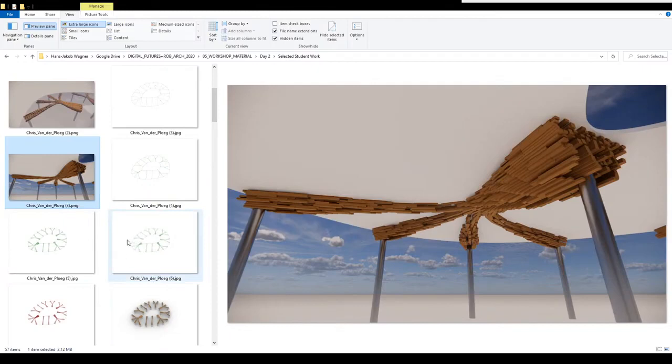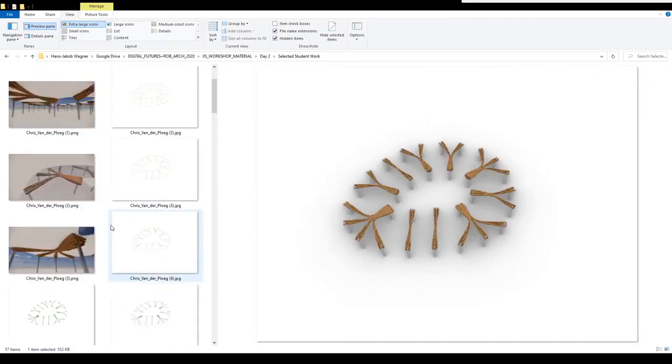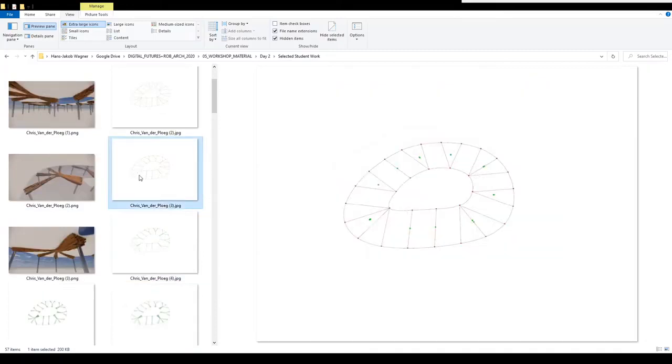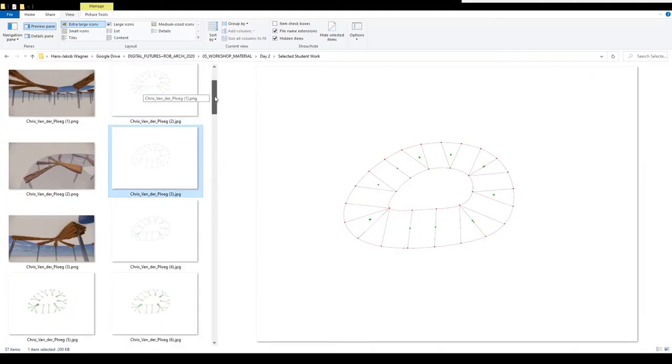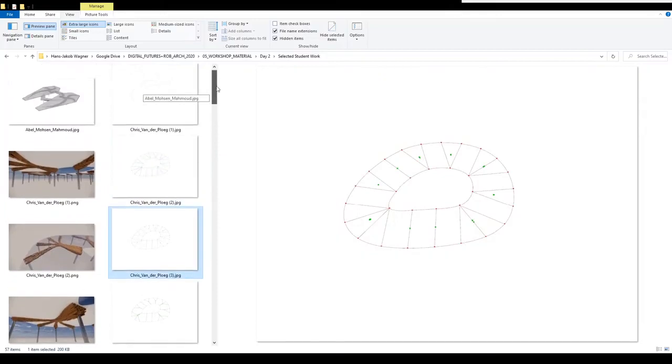Yeah, I can give a short introduction now. What you often see in terms of facades is that there is a certain distance between columns, for example 5 meters, for the inside as well as the outside. But when you have a circular building like this with an inside facade and an outside facade, you have a different number of columns on the inside ring and outside ring, which means that traditionally you would solve it like this with straight beams and putting more structure in it, while the floor itself will not need that span.